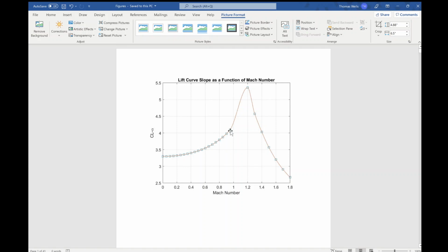But we're looking at a CL max of around 1.5 in combat in order to have such a low wing loading while having such a high instantaneous turn rate. So we're going to need some sort of high lift devices most likely, because judging by this graph, it won't be able to be reached.